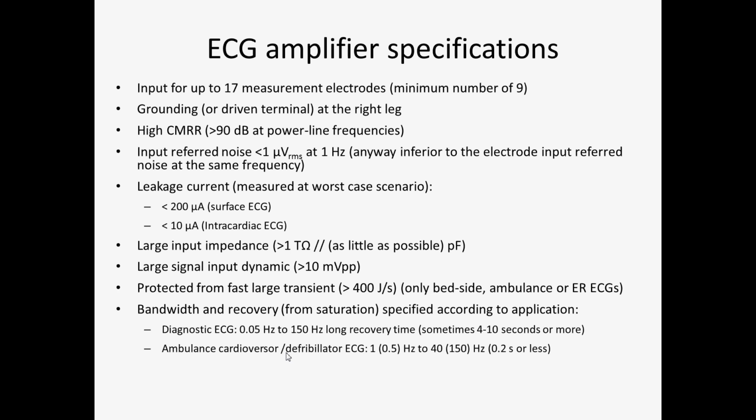Experiments show that if the skin barrier is intact, even hundreds of milliamperes of leakage current over devices are safe. In the case of electrodes, ECG, EEG recording, because you create a preferred pathway to go inside the body, because you're actually probing the signal inside the body, 200 microamperes is the safety threshold.